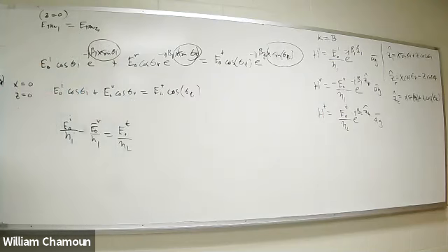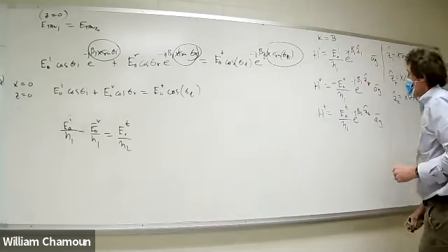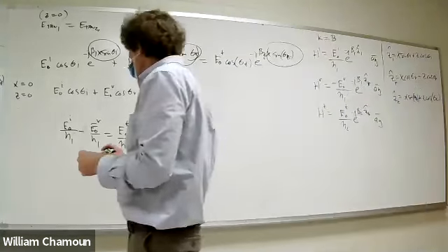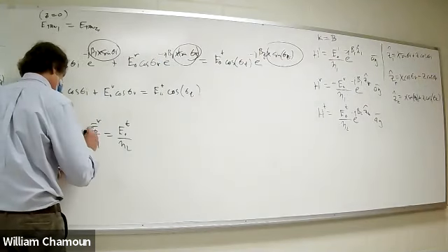The H field is tangent already, right? For the TM mode, it's transverse magnetic, so it's tangent to the boundary. With me? So I just set the exponentials to 0, right, for the incident, reflected, and transmitted. These exponentials go away, and you add them up. The reflected does have a negative sign there. Make that a little more clear.